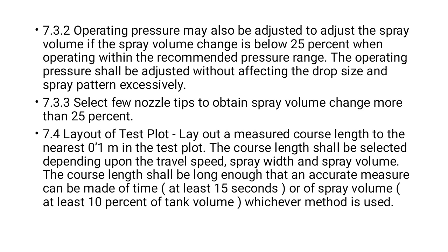Then layout of the test plot: lay out the measured course length to the nearest 0.1 meter in the test plot, and the course length shall be selected depending upon the travel speed, spray width and spray volume. The course length shall be long enough that an accurate measurement can be made of the time or spray volume, at least 10% of the tank volume, whichever method is used. And course length should be to the nearest 1 meter in the test plot.